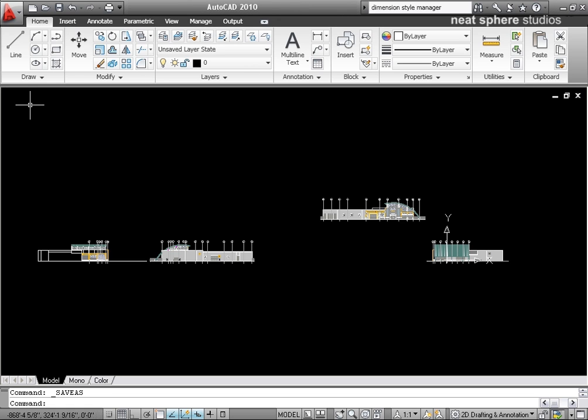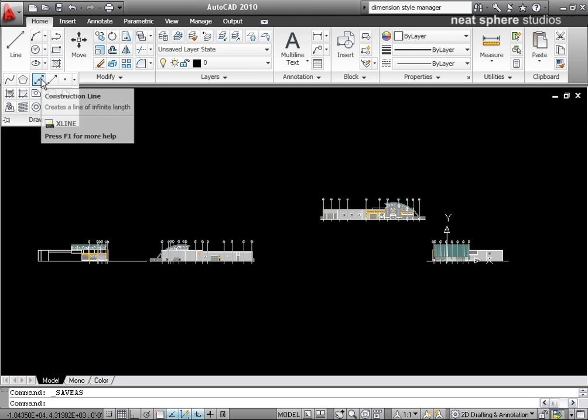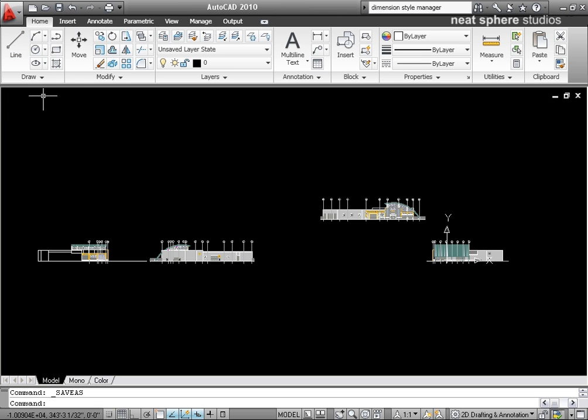What I also have with these toolbars is the word, for example here, Draw, with my drawing toolbar, and then a little arrow. And if I click that arrow, what you'll hopefully be able to see, and I'll pin that there as well, is that there are an extra set of tools within that drawing tab. Now they're not normally shown, so there you go, you can see it's just disappeared back up there. When I press that down arrow, they appear, they stay for a few moments, and then when I mouse away, unless I pin with this little pin here, they will disappear. So it may well seem that they disappear very suddenly. That's because you haven't pinned them.